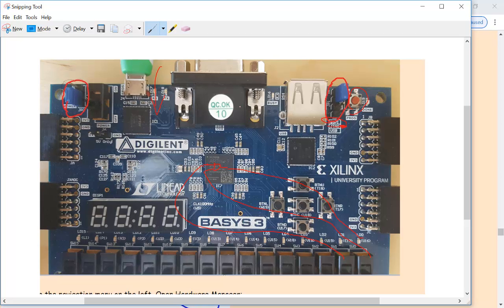Just keep in mind, if you keep this jumper wire here, you will try it, right? So just think about you are the customer. You have a product, even though it's a very simple gate, just an OR gate, and you are not going to upload the code again, program the board again, right? You just program it once, store the bin file in the memory chip, and you power it off and turn it back on, and see if the OR gate is still there. That's what you are expecting, because with any consumer electronics, you turn it off and then turn it back on, the program should still be there, right?